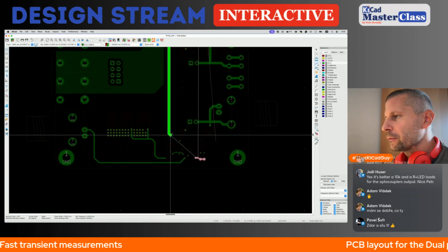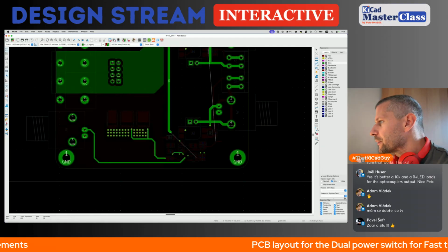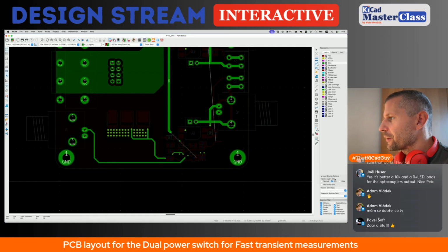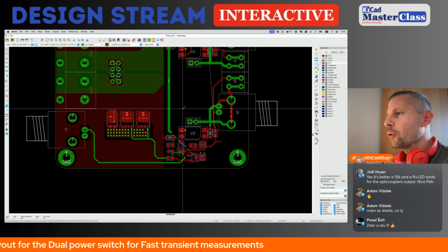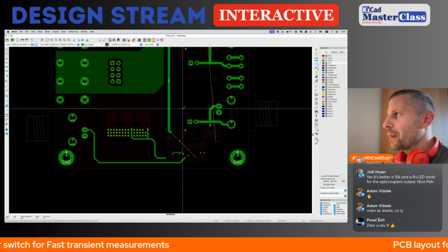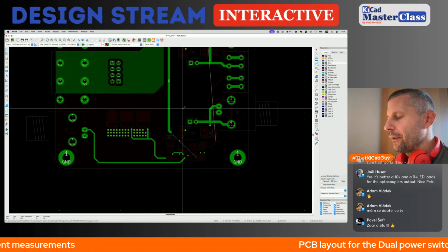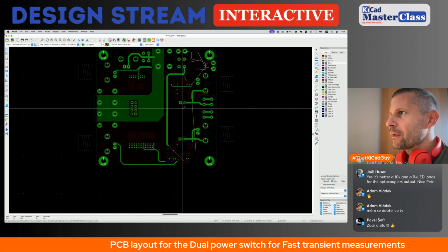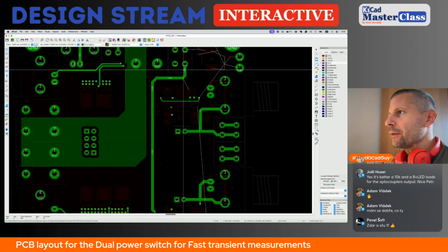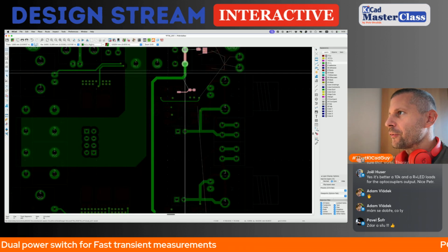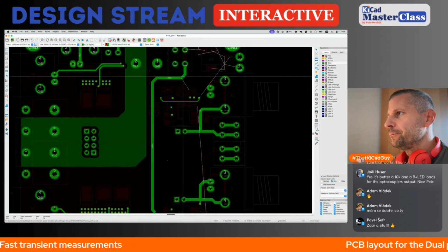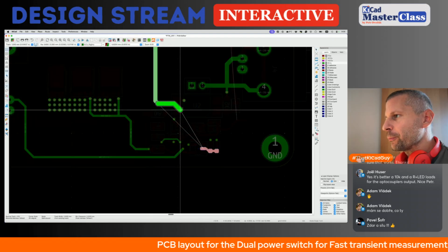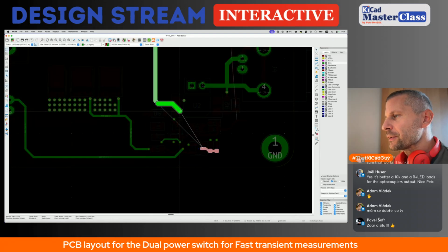Now I'm using the not high contrast mode. It's called dimming of inactive layers by pressing H. Normal is here. Sometimes when the layers are more crowded and I want to see more of the particular layer, it means where are the constraints, where the track can be routed or not, I use the dimmed mode. Now I'm using it for the power line distribution tracks.